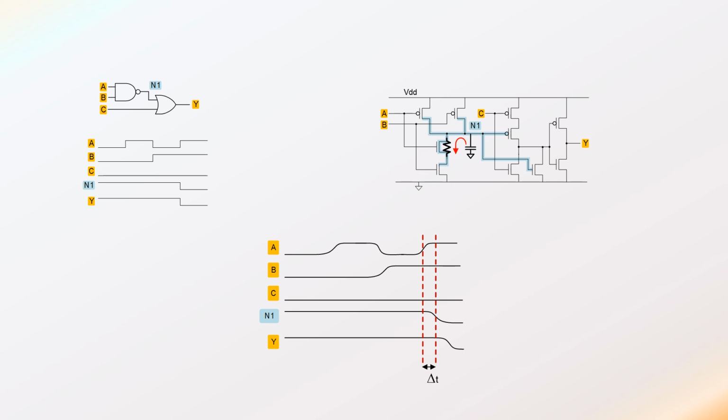And so whenever you see a combinational logic circuit, its outputs are going to be driving other inputs, and those signals that it's driving, those inputs to other gates, are always going to have some amount of capacitance, and we're always going to have to transfer charge from that intra-gate node to VDD or ground, and that's always going to take time.